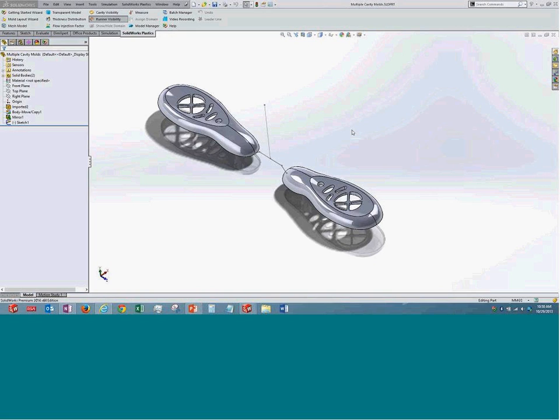Another question: what is the difference between solid and shell mesh? To mesh the model with solid elements, we are using tetrahedral or hex elements. Maybe in the next example, I'll try to show you those elements. When using shell mesh, we are using surface elements. These are 2D elements, or I would say 3D, 2D, wherein we define the thickness of the part using the shell thickness.